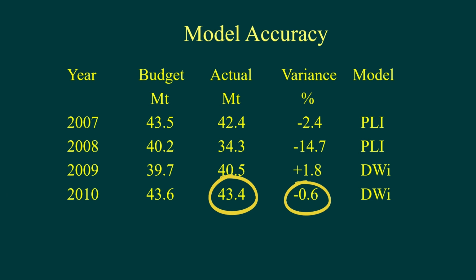So I mean these data, the new model which used the SMC test drop weight index and the ball mill work index to help predict those ball mill limited periods, worked extremely well, and that's as far as the data in the paper went. I've not had any subsequent information back from the mine to see how well that model's going, but certainly on the basis of these last 2 years, it looks to have been doing its job extremely well.